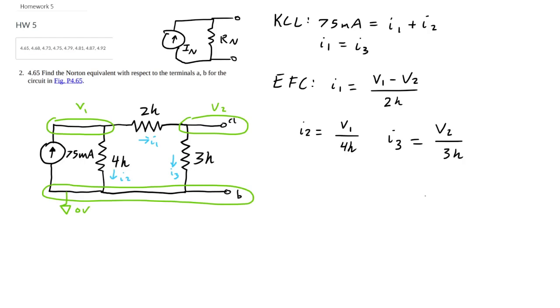So now we're going to do the Norton part. In Norton, we have to make a short circuit current and calculate this. Let me do the little I. Call this ISC, which means we're going to add ISC to this expression. And we're going to begin our analysis. Number one thing we got to realize is when we make this short right here, that's going to make V2 equal to 0 volts because there's going to be the same voltage across here.